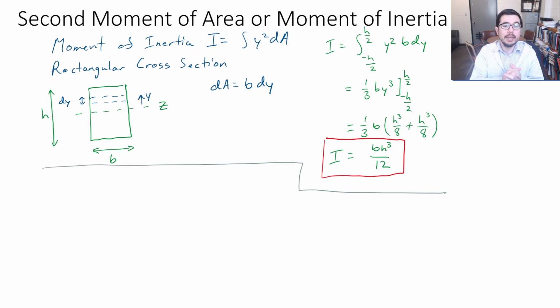posted on the website, talks about what happens if you take a beam and you have it kind of, well, let's put it this way. If you have a beam like this, right, where the thickness is very great and we put a load, say, right there, or if you have it kind of like this, right, where now you have a longer dimension in the b, all right? So look, I is kind of an indicator of how much it resists bending, and the bending stress will be inversely proportional to this quantity.